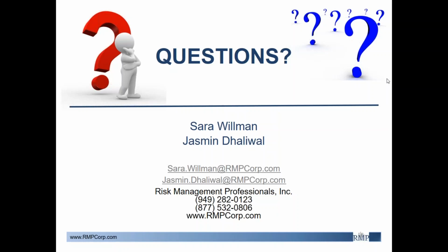Thank you. When is the best time to implement ISD principles in an operating plant? Okay, so of course, the best time to implement these is usually in the design phase, before anything's been completely built or designed. You want to analyze these principles so that you can incorporate this more easily before things actually start up. But that doesn't mean that you can't incorporate these principles throughout the life cycle of the process.